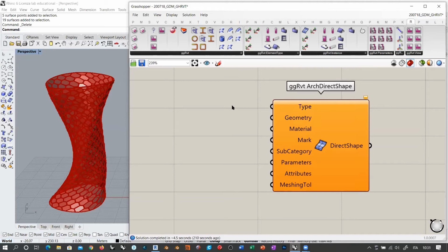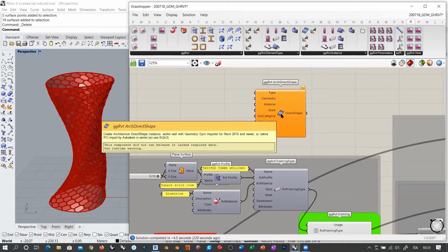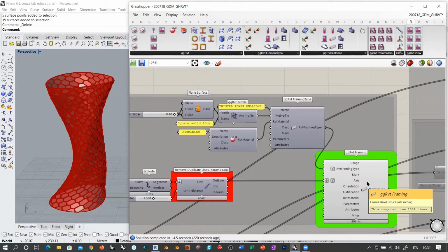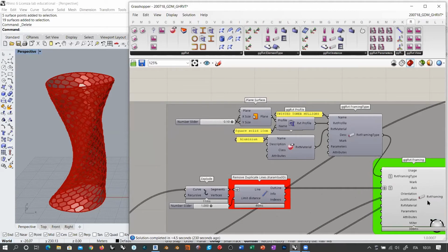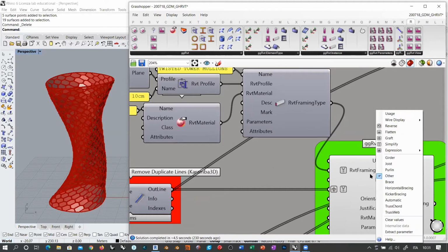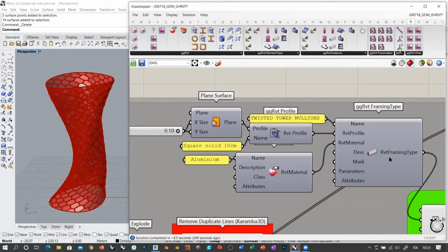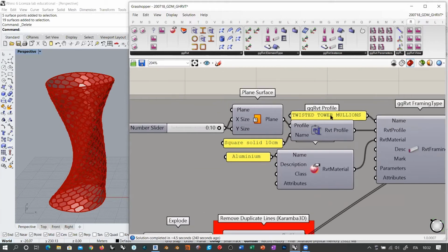I already spoke about this with John, of course, and he's going to take a look into this as soon as possible. But he always told me there is a workaround. You can use standard framing, and actually it works. You see that these beams here are not actually beams. If you define other, basically you are bypassing Revit's controls over the actual aspect or function of a beam. So you can use this, define the standard Revit framing type, giving it a name, and also defining the proper cross section.